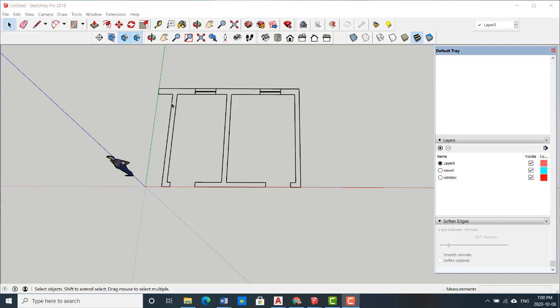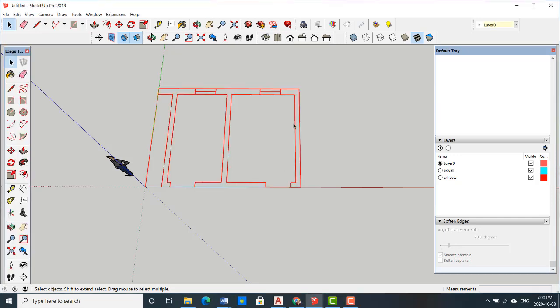After you import your AutoCAD drawing to your SketchUp, the next step is checking the size of the wall or anything that you can just measure. Make sure it's the right size, then you make sure it's a group, then you lock it. Next step, I want you guys to redo all walls.